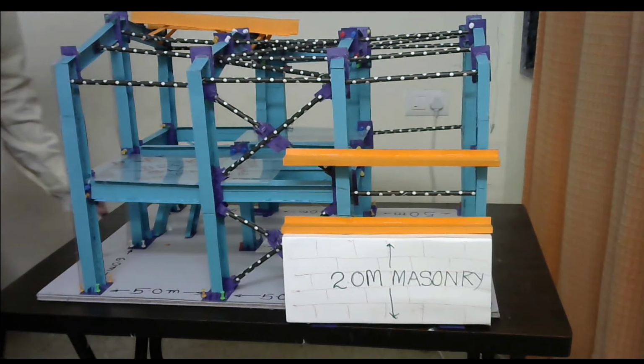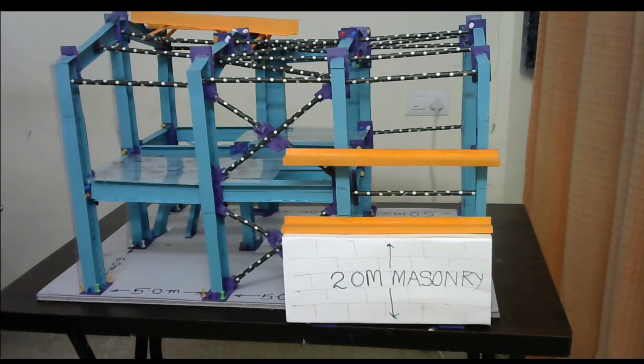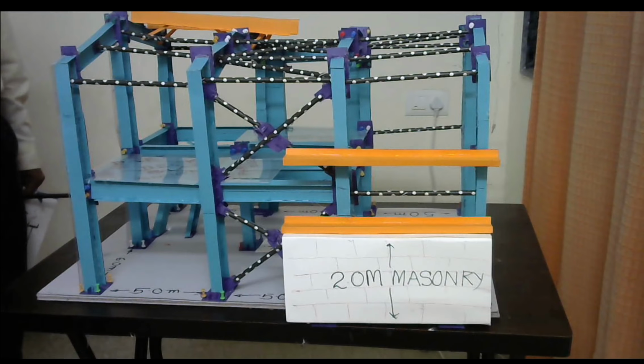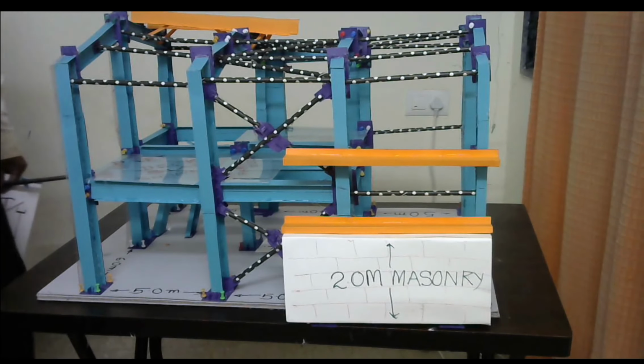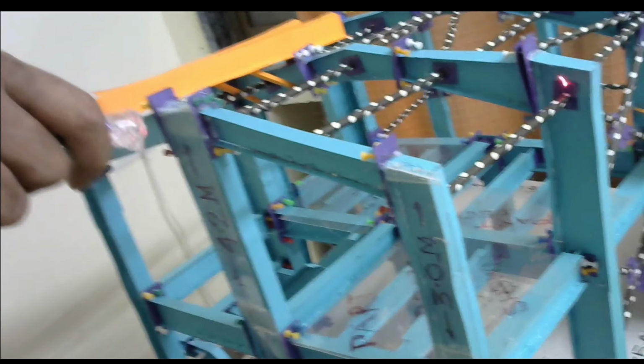So let us come to the rafter now. If you can see the flange braces, if these purlins are providing flange braces, LX and LY will be center to center between these flange braces. If they are at 1.5 meter center to center, LX and LY will be 1.5 meter. But the LZ parameter, now see, we have to consider there is a kink here, and I can consider this joint similar to the joint here.